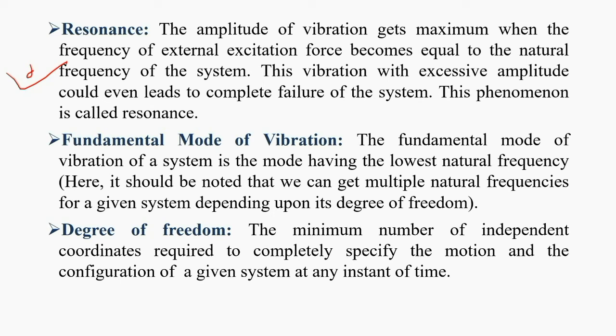So it means the designer should design any system such that the natural frequency of that system does not lie within the range of the external excitation force frequency. It means it should not lie within the working frequency of that system. Okay, that is resonance. Okay, next one, that is fundamental mode of vibration. Fundamental mode of vibration is nothing but the mode having the lowest natural frequency.